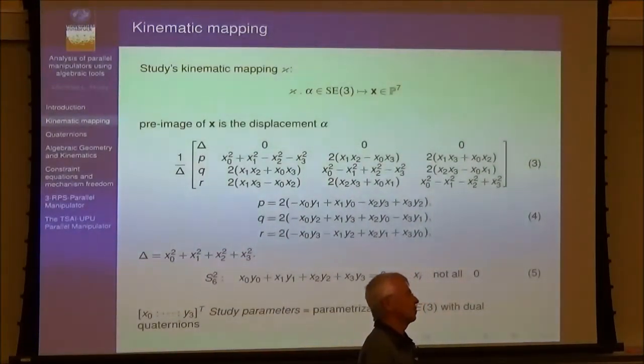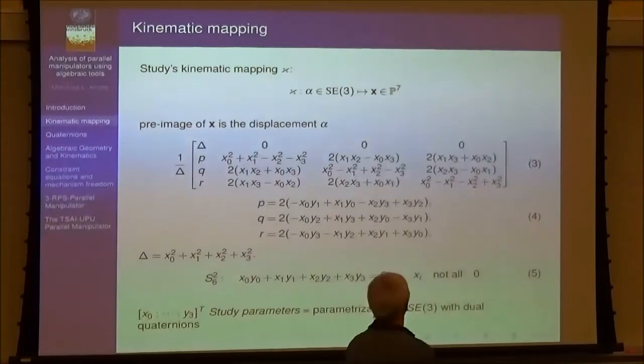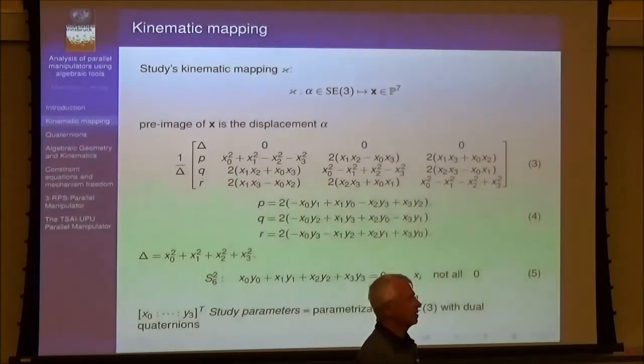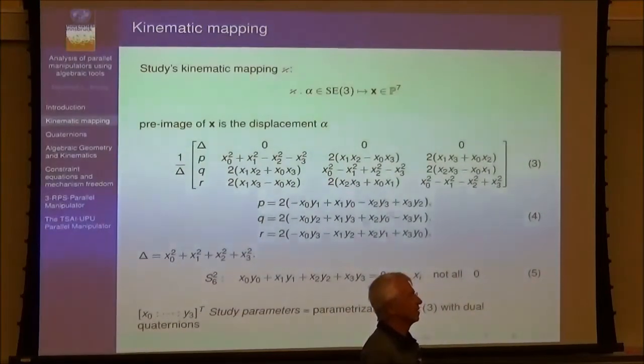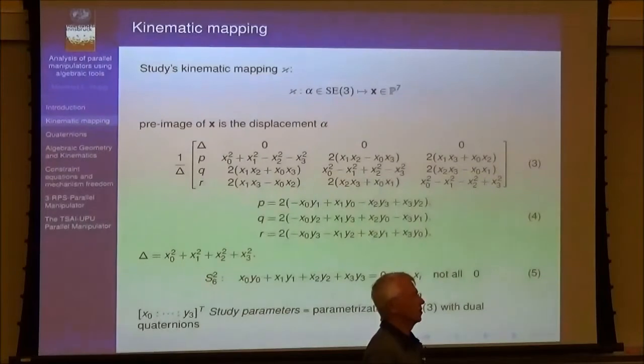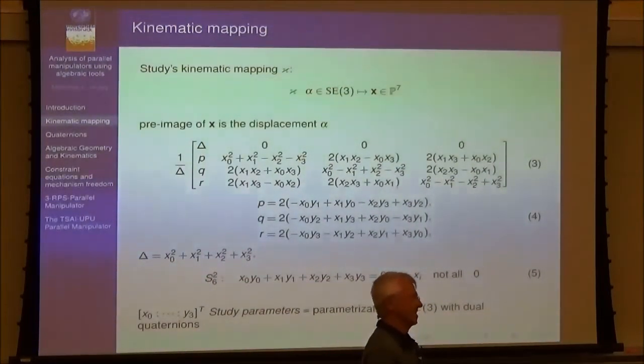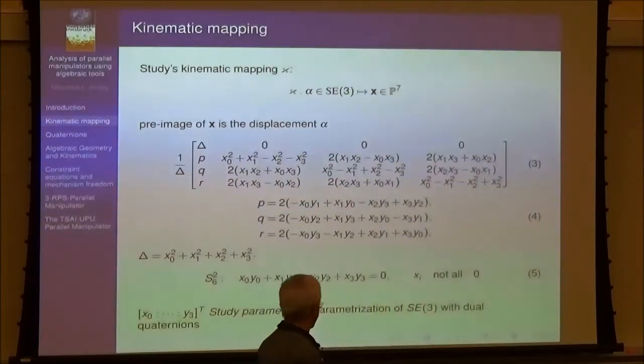The point does not represent a motion. The PQR you will get, yes. But when you substitute everything back, you still get the valid Euclidean displacement, once you are out of the Study quadric. No, you still get it. That's something that I'll show you.